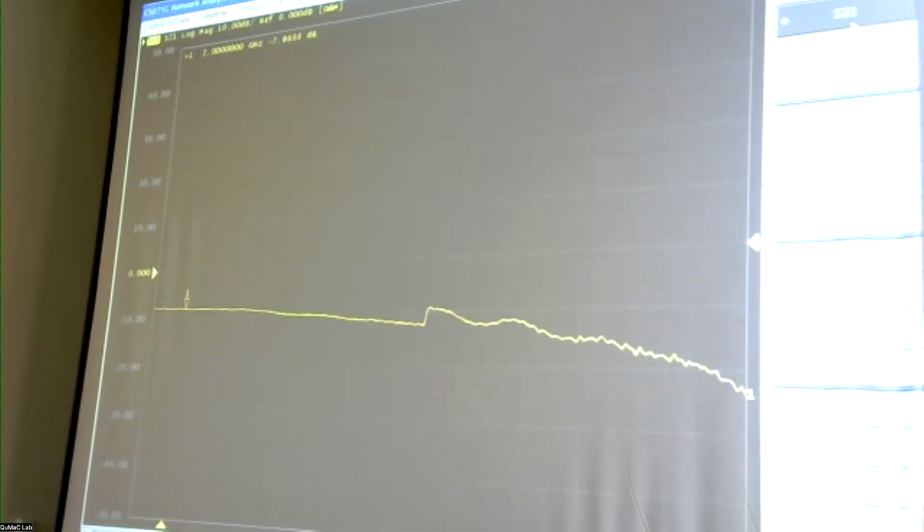But you know those numbers, and if you know that, then by measuring the scattering parameters for these idealized loads, you can back calculate the S matrix of the middle part and remove it from the calculation. And this is actually what the calibration procedure is. So there is a menu here.